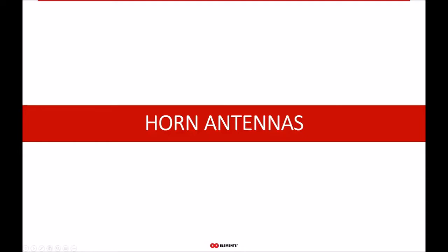As advertised, this webinar will be about horns, and we'll look at horns from the angle of WISP networks, which means that we use the filter of the conditions that WISPs are dealing with in the unlicensed 5 GHz band. This is a very specific lens through which to look at horns, and it would be quite different in a different industry or different frequency band. But to make this webinar as relevant as possible to you, we focus on 5 gigahertz unlicensed band WISP networks, which WISPs rely on a lot.